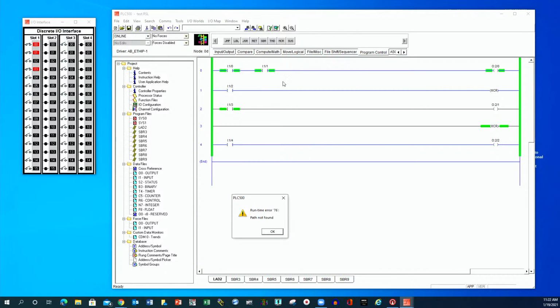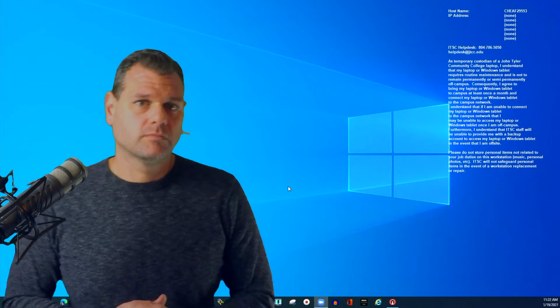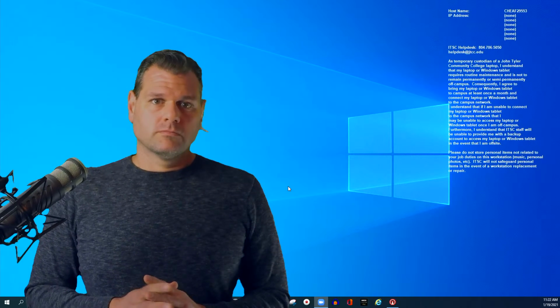But basically, if it's within this fence, this line has to be true in order for whatever is between these two to be active. If I was to be able to turn on 1, 2, you would see the MCR come on, and then the output would instantly come on. If this is still true and the zone goes off, then you'll see the exact opposite.